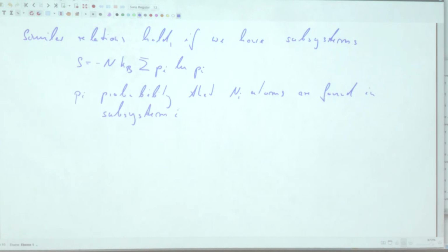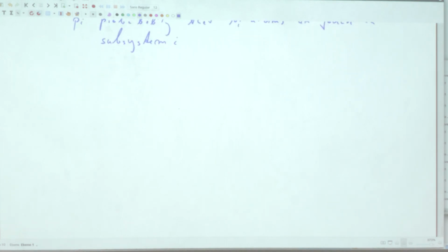We have all our atoms, and they are more or less sitting in potential minima. And once in a while, an atom jumps to a neighboring site if there is a vacant site. So what's the probability that this special atom acquires sufficient energy to overcome the barriers around it? That's the so-called Boltzmann probability, of which I sketch the derivation here.